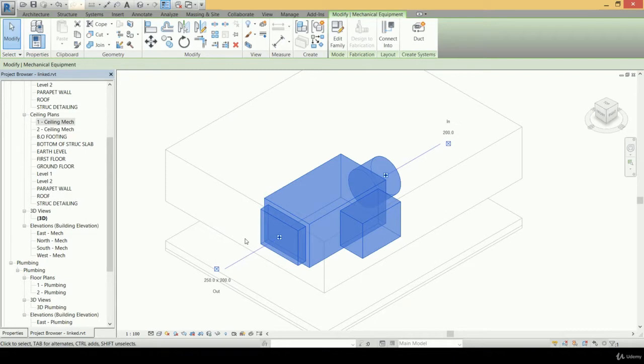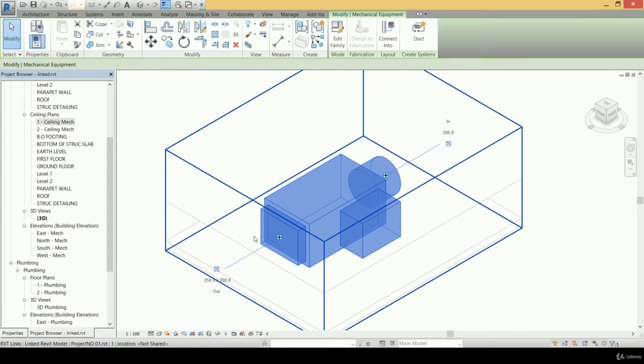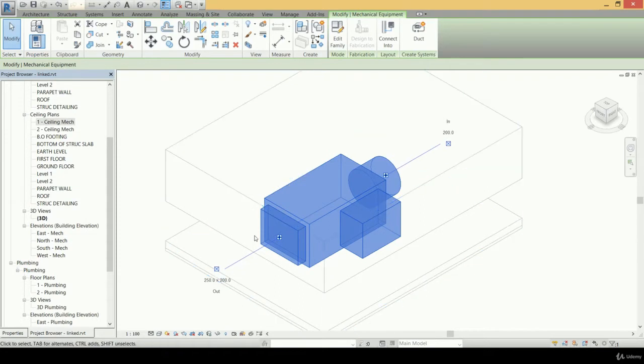So it receives the air from its input, then it controls the amount that will flow out of it, as it has some dampers. This is because it's a variable air volume box, so the dampers control the amount of air flowing through it, and then it goes forward through the output to feed the branched ducts and to feed the zone we have. Very good.